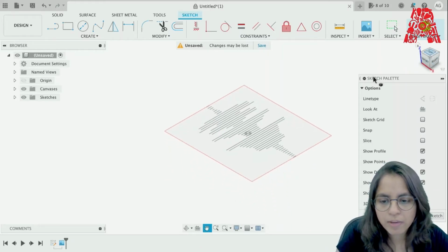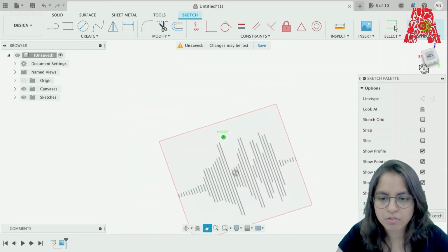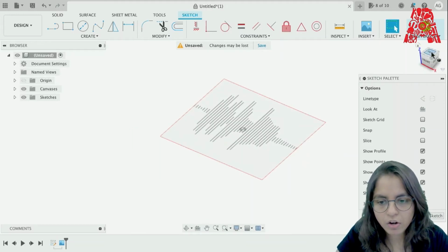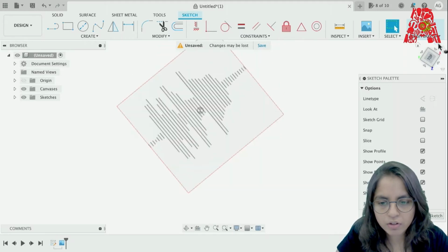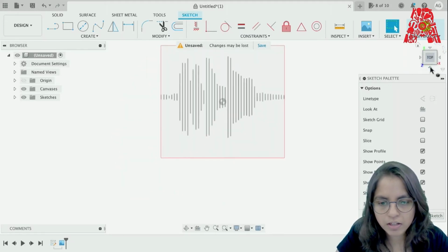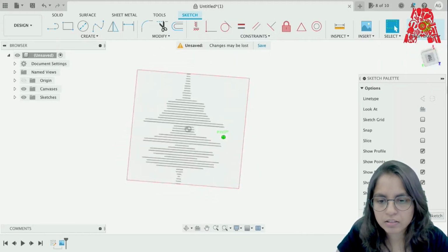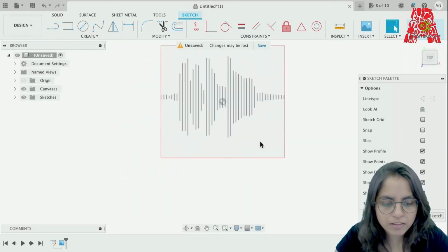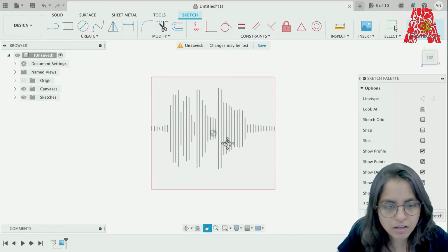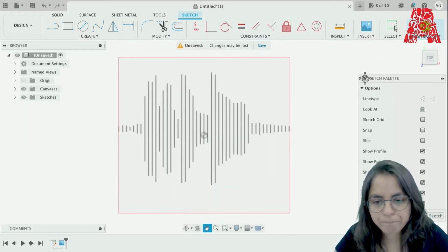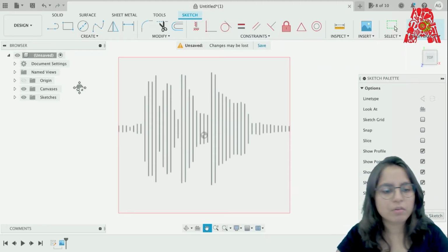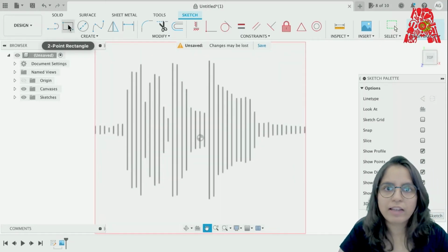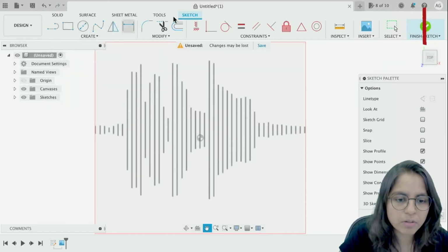So the way that we can change the orientation is by using this side one, this cube on the right. We can also click on top or click on these orientations, or we can manually move them like this. I'm going to select top and then change the direction to this so that we can sketch it out. But yeah, this is the main basic stuff. So now what we want to do is sketch this out, as in I'm going to use a 2 point rectangle here. But let's see what other options are available under sketch.